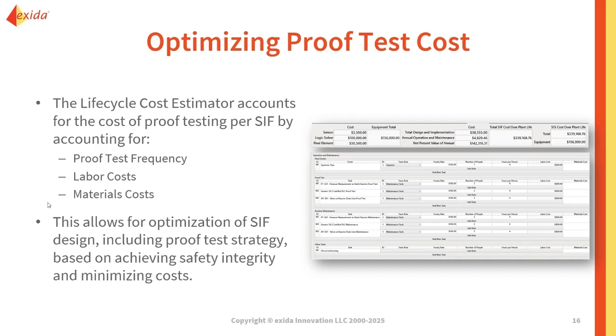If you're having trouble meeting your safety integrity requirements, you might have to decide, should we add redundancy within our SIF, or should we do more frequent testing of our SIF? And this module is going to help to understand which has a larger impact on your overall costs, to ensure that you're able to consider that as well as meeting your SIF design requirements.